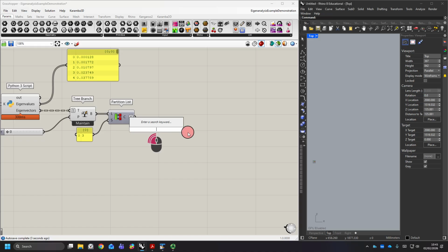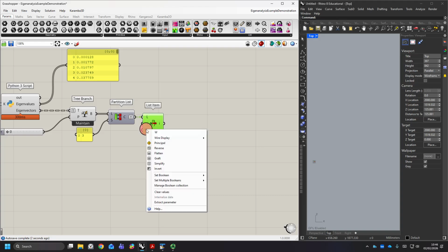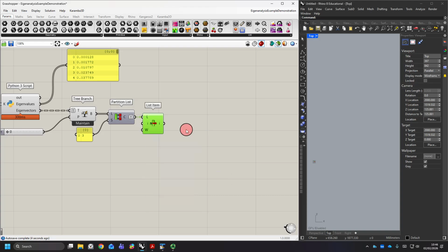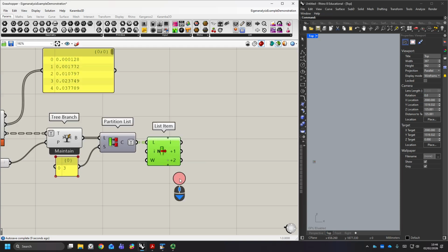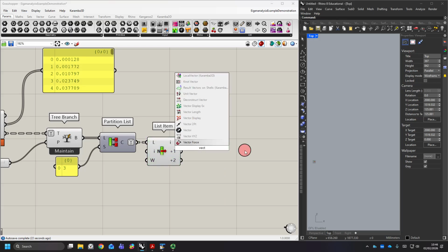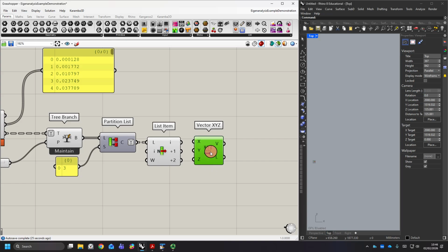So then the list items, what I'm aiming to do is create a vector, which is how I'm then going to display everything. So I want to run my list in here. I am just going to turn off the wrapping, and then I can zoom in here. So I have basically the displacements in the x direction, displacements in the y direction, and then rotation around the z-axis. And what I want is just to define my vector.